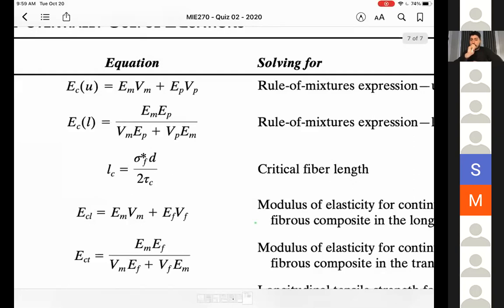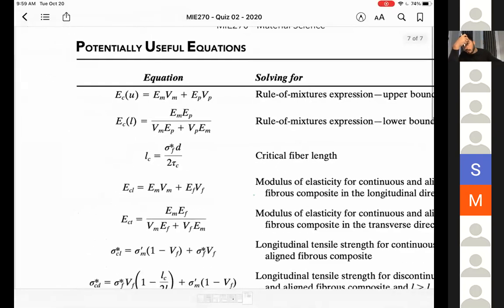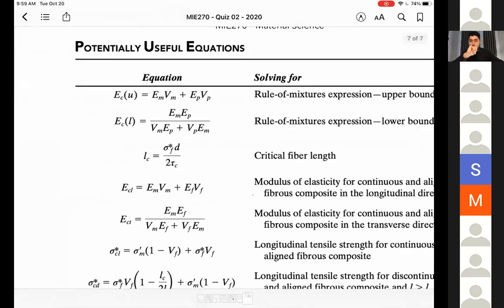So she gave you a formula to calculate the shear stress? No, she just said it was, hold on, give me one second. Yeah, no problem. Show me what you're looking at. She gave us that formula and she said tau is the minimum of the fiber matrix bond strength and the matrix shear strength. So whichever one is lower, that's the one you're going to put in. Oh, okay. So between those two values, let's say we were given those two and one was smaller than the other, we would just pick the smaller one. Yes, absolutely. Actually, that's a really good test question, to be honest, because that just checks your understanding if you know which one to choose.